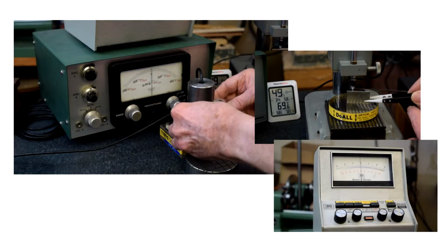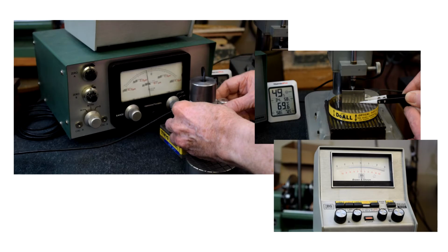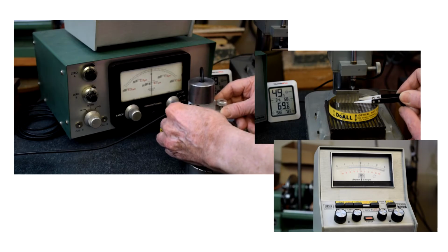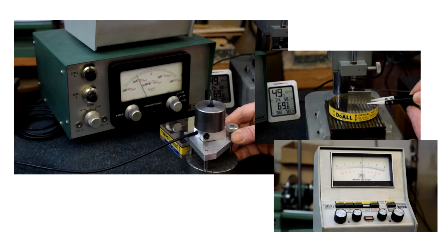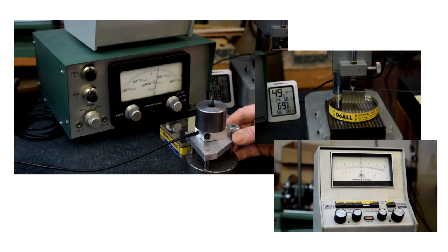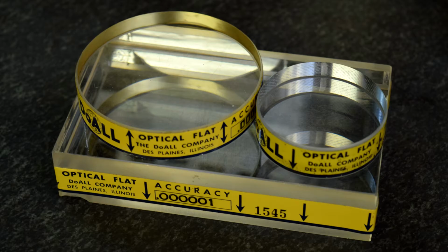While it's not difficult to make measurements in the 40 microinch range, about a micron, or even better, with a variety of indicator and instrument setups such as these, measurements in the, say, 4 microinch range, a tenth of a micron, can be difficult without very good setups. But it's fairly easy to make measurements to a few microinches with an optical flat, just a transparent piece of fused quartz with at least one surface lapped to about a microinch.